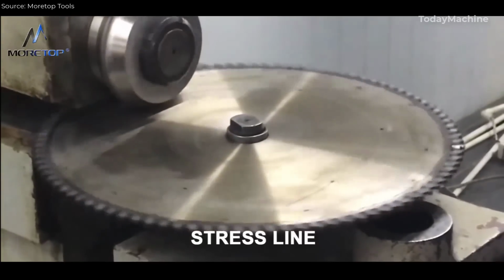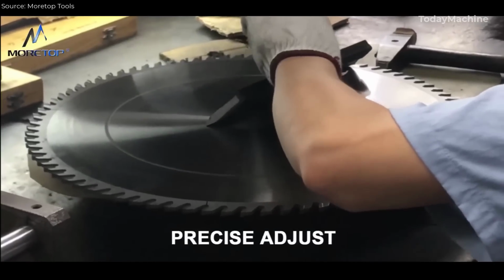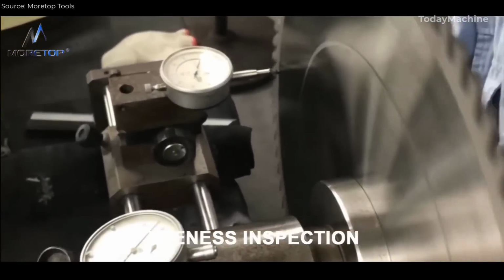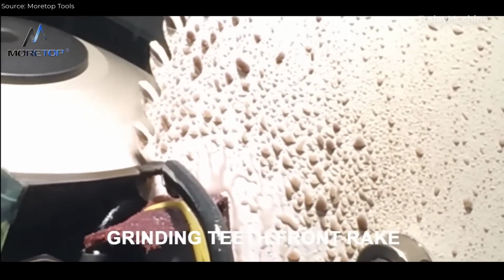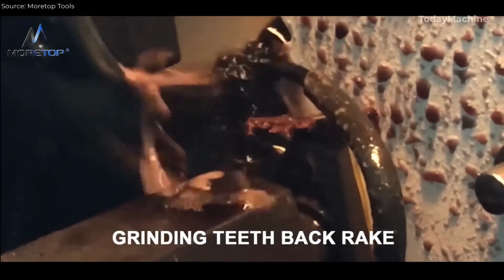Precision manufacturing. The precision of circular saw blades has been enhanced through advancements in computer numerical control (CNC) machining. CNC machines can produce saw blades with tolerances as low as plus or minus 0.005 millimeters, ensuring consistent quality and performance. The ability to control every aspect of the manufacturing process, from the grinding of the teeth to the balancing of the blade, allows manufacturers to produce blades with exceptional accuracy. This level of precision is crucial in applications where even slight deviations can lead to poor cuts or material wastage.